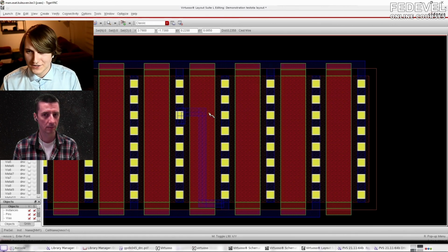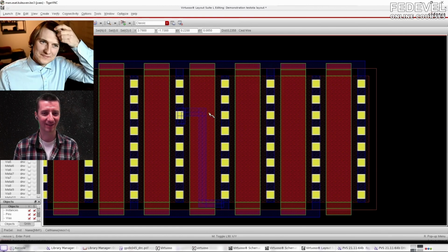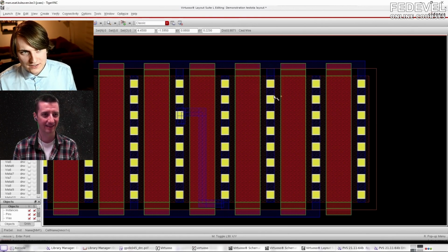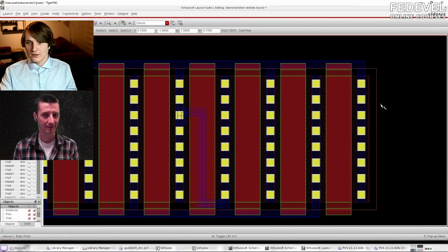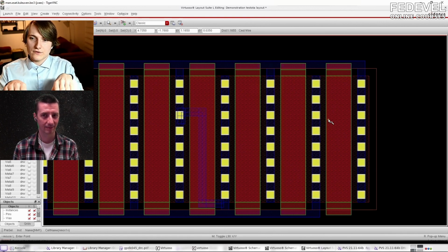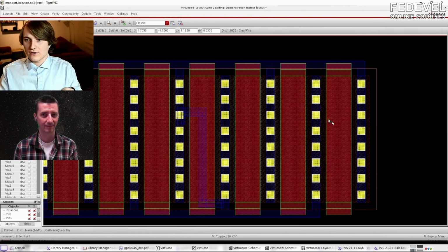I forgot how we got here. We got here because you showed all the parameters of the transistor. Exactly. Yes, exactly. So this might be something that is modeled in one of these parameters, is how this influences these things. Okay. It's even the case that the direction of the current on the chip might have an impact. So if current flows from left to right, the transistor might behave slightly differently than if the current flows from right to left, because of how the dopants have been patterned.